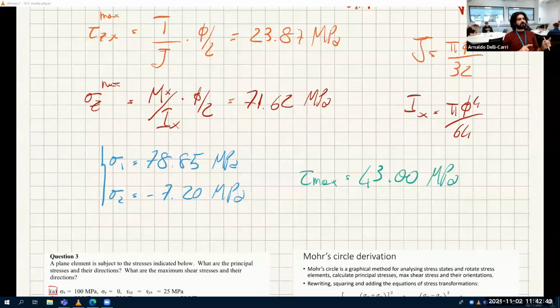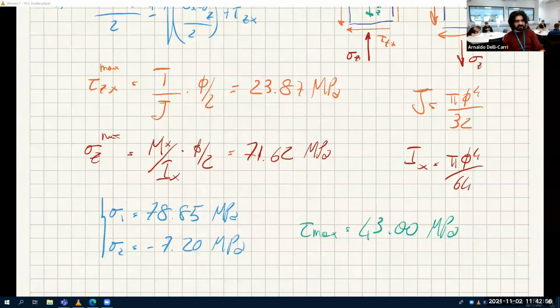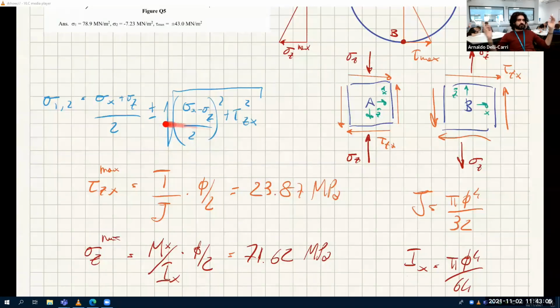So you start from the back: you start from the safety factor, find sigma 1 and sigma 2, then sigma x, and find the most stressed point. Those stresses contain the diameter, so your unknown is inside this large equation in a single unknown, which you can solve with MATLAB, or by hand if it's easy enough. Okay, good.